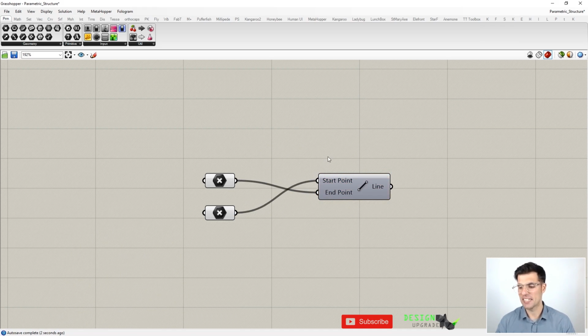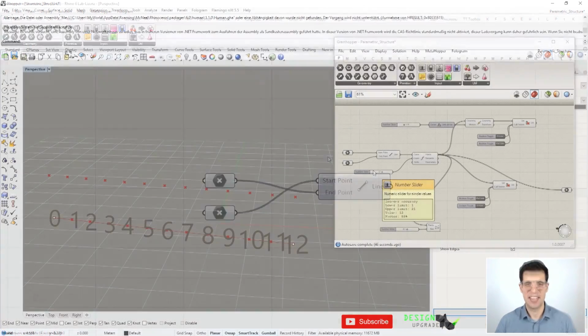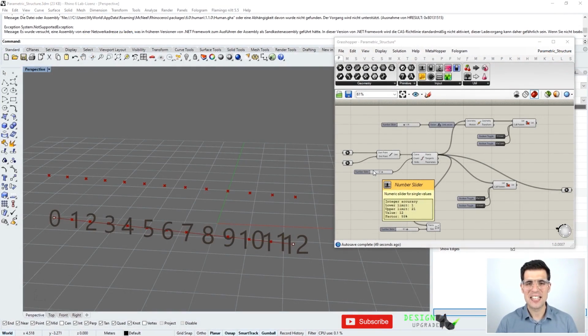And now let's get back to our Grasshopper definition. Now we are going to start connecting the nodes of our Truss structure. You already know how to manipulate lists in Grasshopper, and now we are going to combine different lists into the same Grasshopper components. So let's start by taking a look at the most simple case, which is when the two lists have the same amount of items.